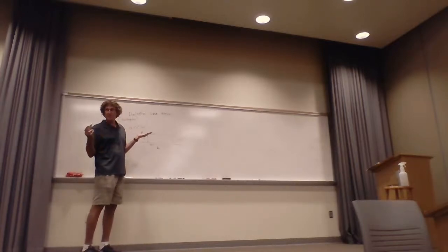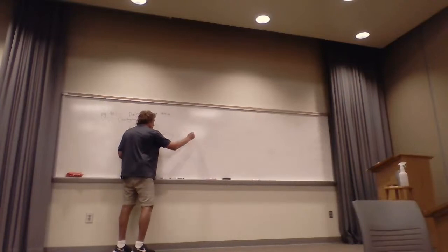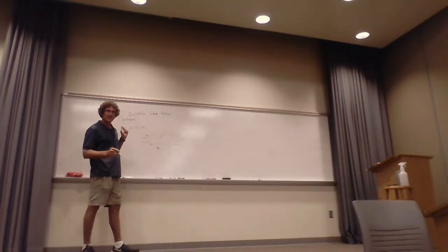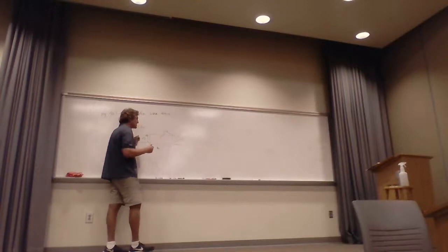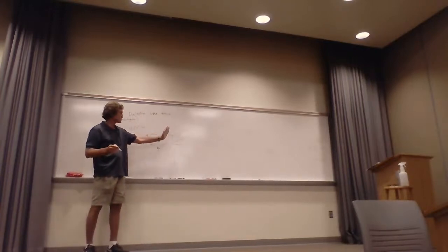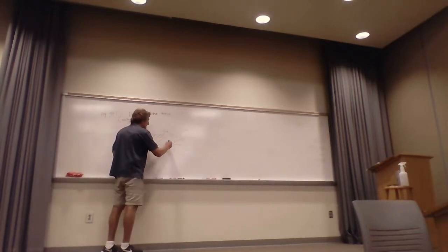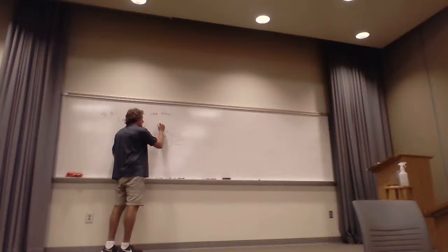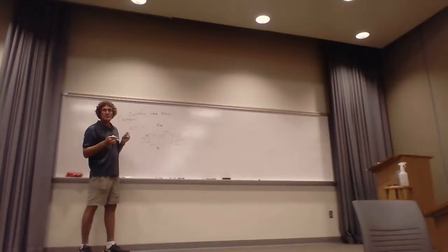It's transparent, all right? But it is a dielectric, so it has very low loss. What happens is the wave, just like the rectangular guide, bounces up and down between the plates and flies down there. But because it's a dielectric guide, there is no boundary condition that the electric field be tangent to these regions. You could say this thing's made of quartz or something like that. And then the surrounding material is air. There's nothing that says the electric field has to go to zero there. Y'all follow me on this?